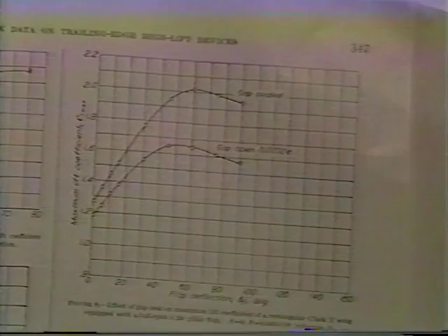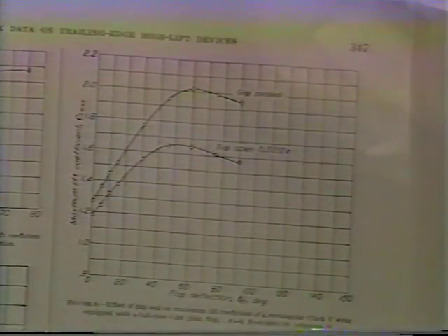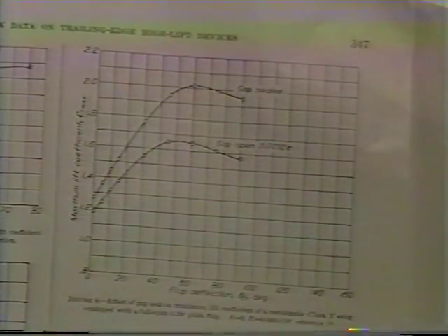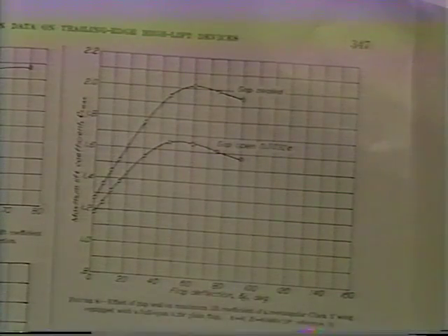And whether it's a Clark Y airfoil or a 4-digit series or a 64 series laminar flow, on a plain flap, and this is true for an aileron, on a plain aileron, sealing the gap has a definite improvement both in maximum lift coefficient, flaps up or flaps down, and even on drag. So sealing the gap on that type of arrangement is quite important.